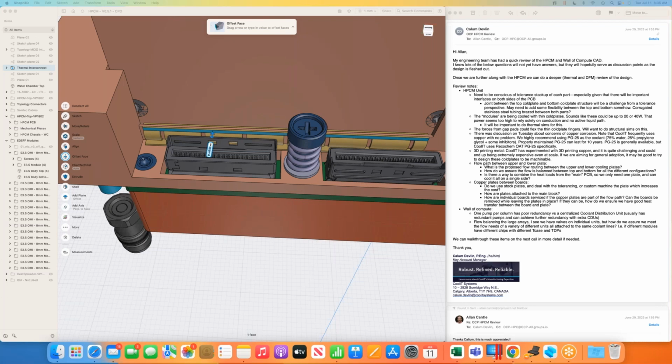That's where I said we need to maybe put the gap pad between the spring and the copper plate, so this spring loading actually compresses the gap pad, and how effective would that be or not, as the case may be. Yeah, so companies can help us make these little assemblies. And so where you'd also have the gap pad, Alan, is on the surface of that copper as well, connecting to the card. Now that's a bit more challenging because this module is going to slide in from the top.